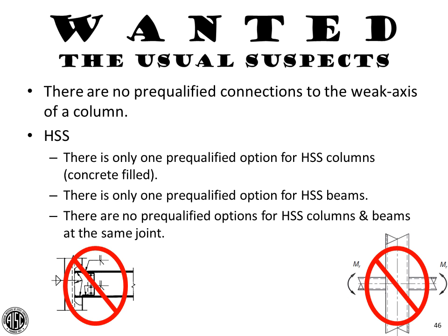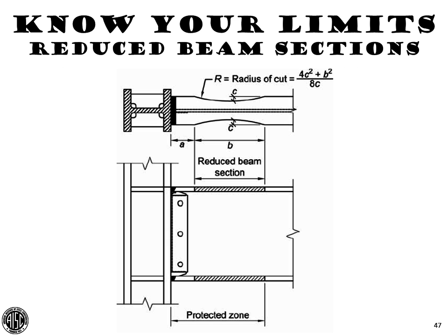Now, if you can use an ordinary moment frame, then that's a good way to use an HSS. That's a good option. When you get into these special and intermediate moment frames, you can run into a lot more problems there.